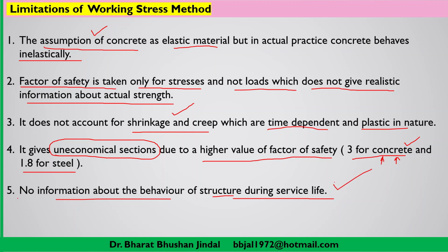All this information is not available in the working stress method, because the working stress method mainly focuses on the strength of the structural element, but not on the behavior of the structural element when it is in practice.